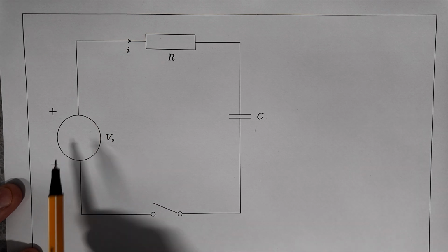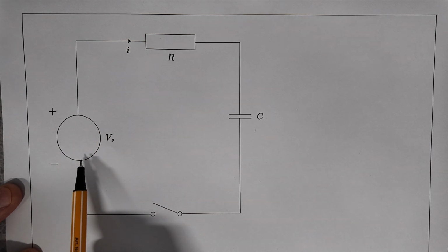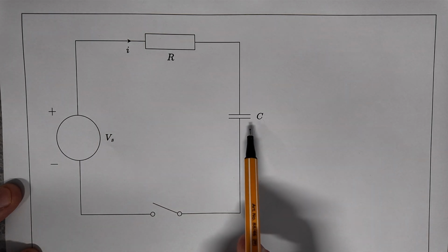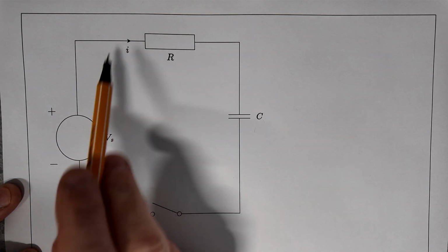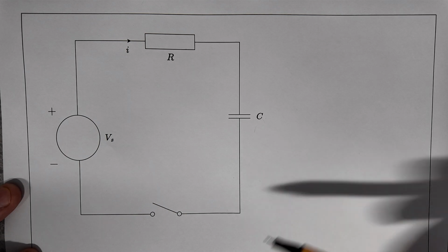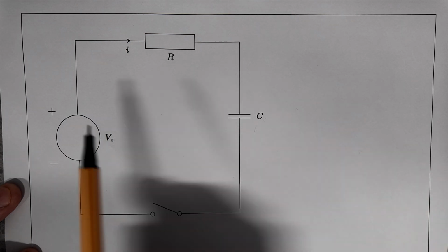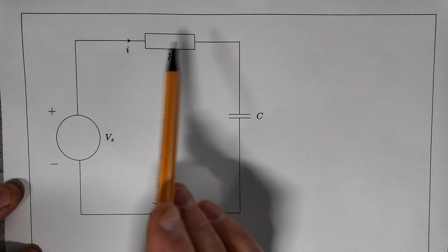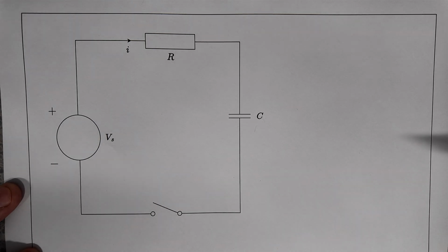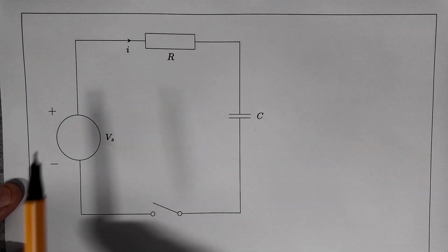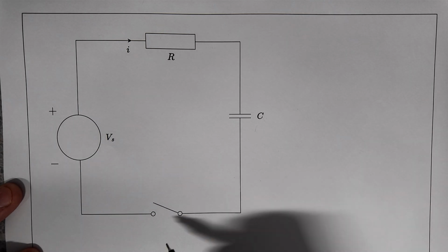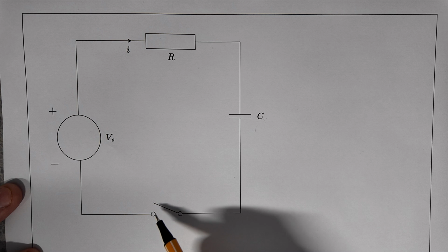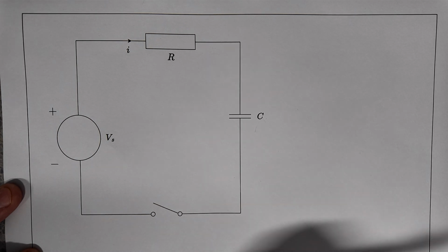So just to explain this circuit, this is a DC voltage source, this is a capacitor of some capacitance C, and there's a resistance. There's always a resistance in a real circuit, and when you do this kind of analysis, if you don't have a resistance and you have an ideal voltage source, you can end up with very intractable problems. So it's always good to have a resistor, even if it's very, very small, when you're doing this kind of analysis. So we're only interested in the behaviour of the circuit once the switch is closed.